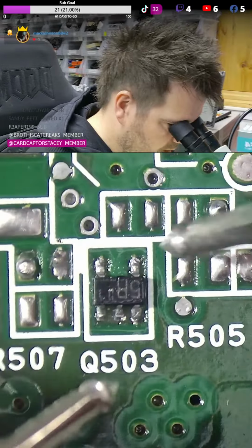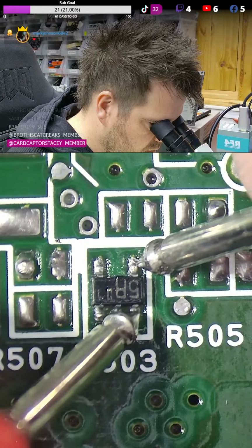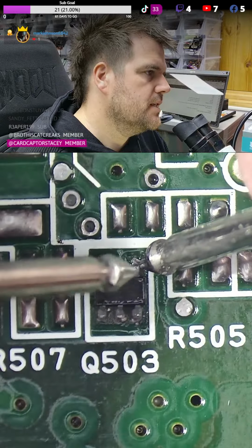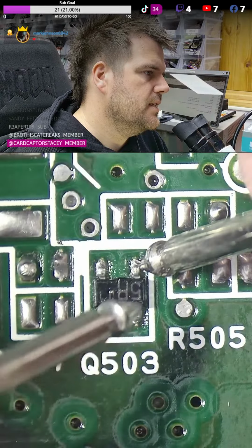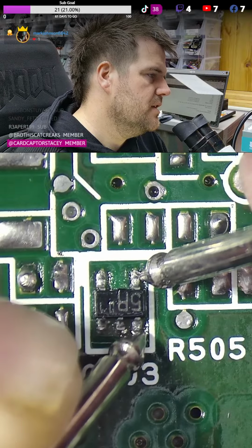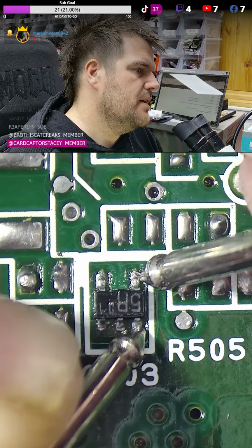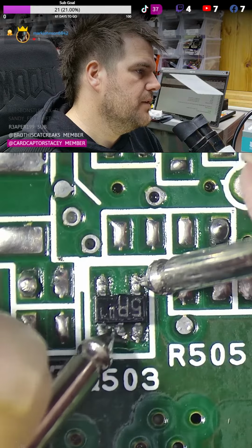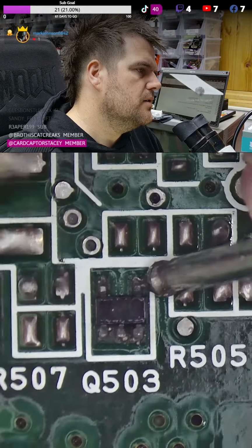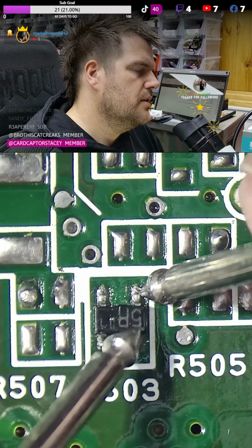So, now let's see. We did have a beep, I'm sure. There we go. So, there to there. So this is our cathode, this is an anode. So we have a diode in here. The fact it's Q, it's going to be a transistor. So we're going to have either an NPN or a PNP. We don't know which yet. So there's one there. So that's one.